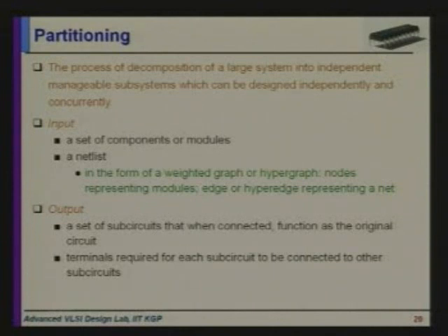It is in the form of a weighted graph or hypergraph, with the nodes representing modules and an edge or hyperedge representing a net. So what is a hypergraph? A hypergraph is a set of vertices, and the edges are also subsets of the set of vertices. For example, say I want to define a net. A net may not be just connecting two components. A net can be connecting numerous components.